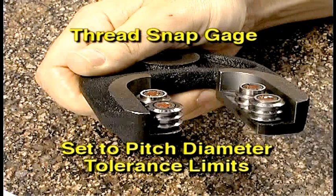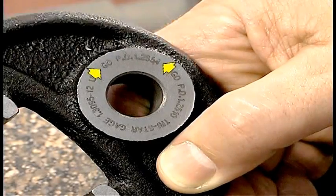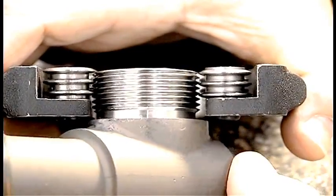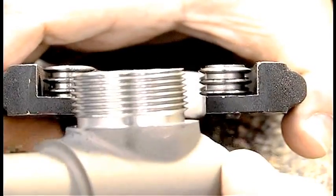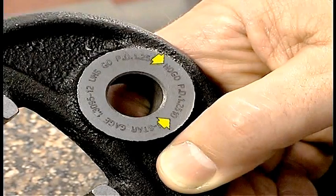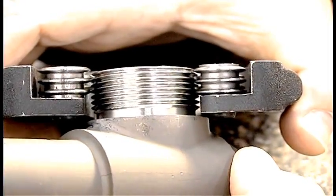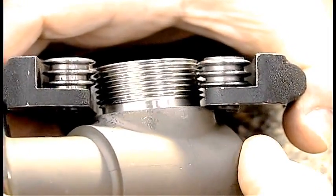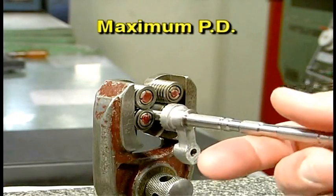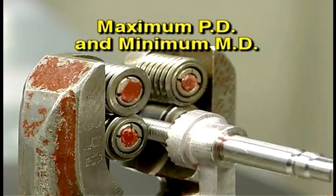This gauge has 2 preset gauge points. The top gauge is the go gauge, which is set to the upper limit of the pitch diameter. If the workpiece passes this gauge, the pitch diameter is not oversize. The lower gauge is a set of rolls set to the lower limit of the pitch diameter. If the piece passes these no-go rolls, the pitch diameter is undersize. This gauge checks the maximum pitch diameter on the go gauge and the minimum major diameter on the no-go gauge.